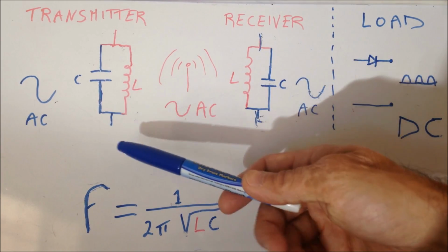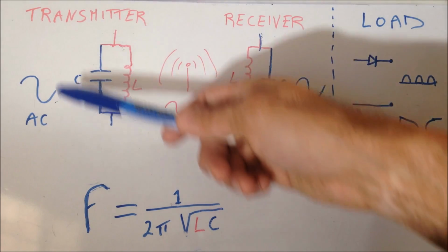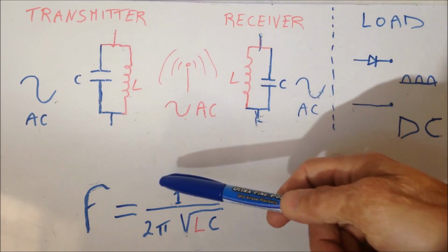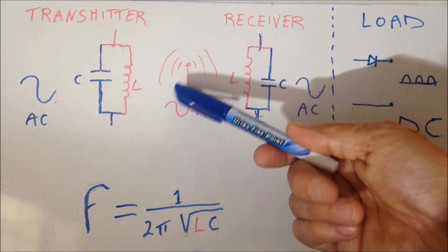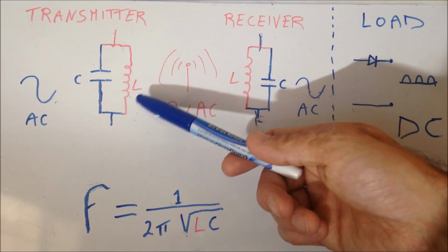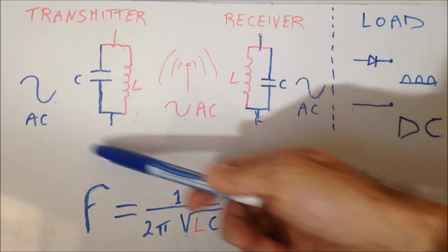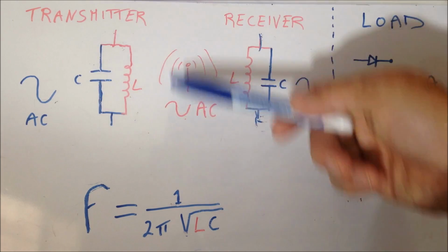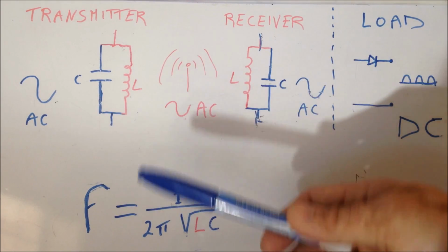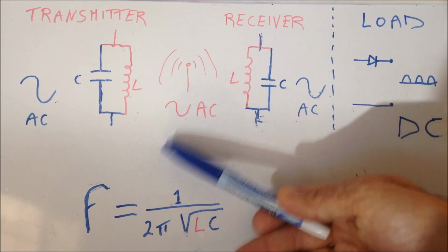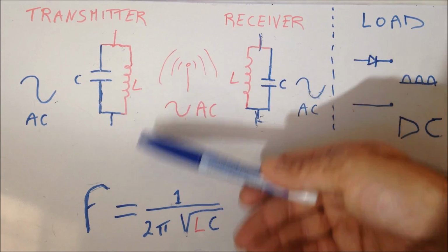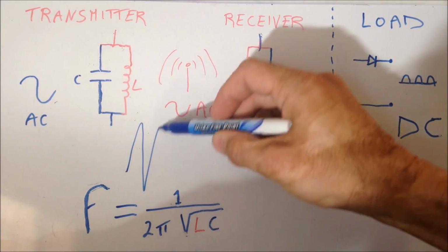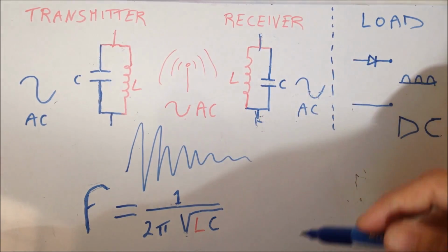Yes. So what's the theory behind it? Once you apply a charge to the capacitance, the capacitance is going to discharge all the energy into the inductance. The inductance finally creates a magnetic field around it that creates an equal and opposite charge to our capacitance, which will eventually recharge and discharge in an endless loop. Well, endless loop is a little bit too much, since we know that a perfect capacitance and a perfect inductance don't really exist. So all the energy is going to get lost in a classic resonance waveform.